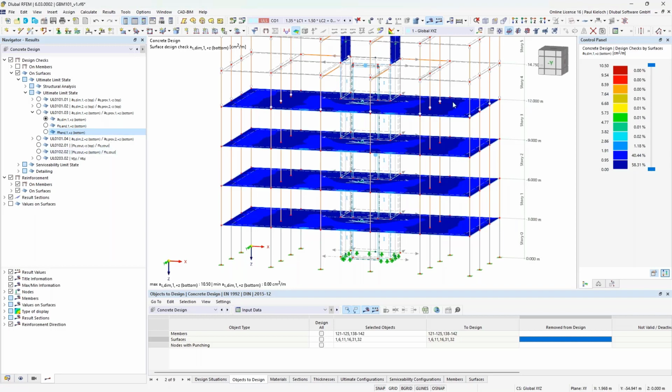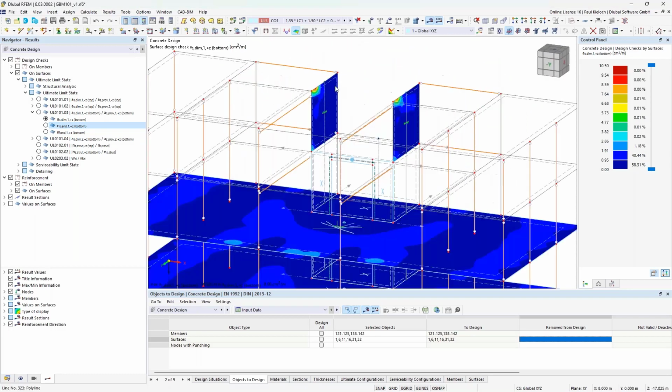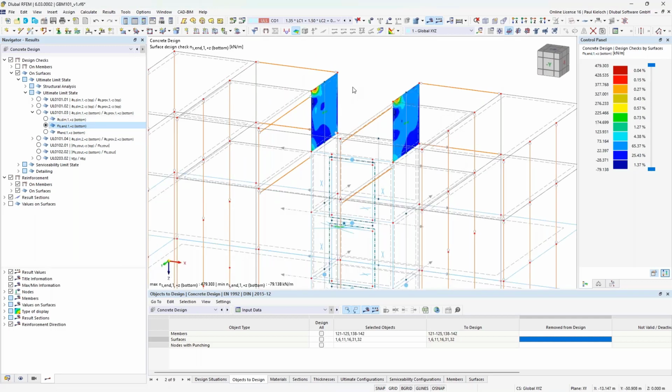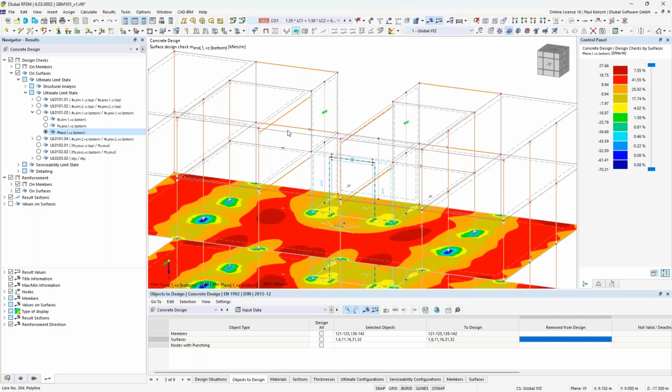So we have now inside a 3D object or 3D structure a separation between design membrane forces and design moments. So for these regular walls on this end, that's why I've selected randomly these two slabs here, we have this regular design membrane forces. So it's like you would design regular 3D objects. And this new setting here in context of a 3D file is the design moment.